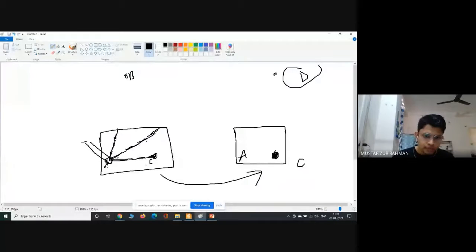But then we have A point and we have the C point. Again, we can look towards the C point, but here we can go to the C point. We can measure the distance of this C point. So we will measure the distance of this C point and we will draw it in a proper scale. Then the plane table moves to the C point.